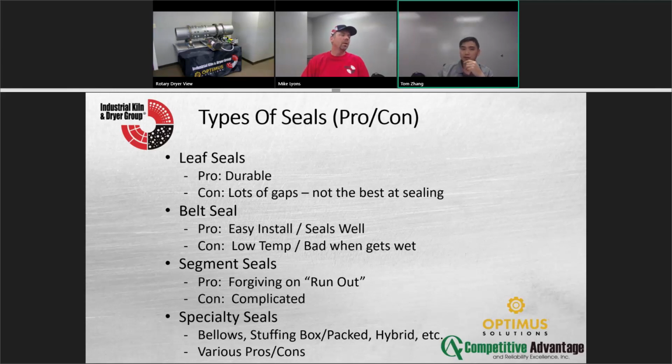And we'll have some pictures after this. You get some flexibility with the leaf seals too. Right. And maybe 90%, it's relatively efficient. I wouldn't say it's... if you have a gas that you don't want to leak even a little bit, this is probably not the seal design. But typically that's what I would say is the most common. We see that quite a bit.